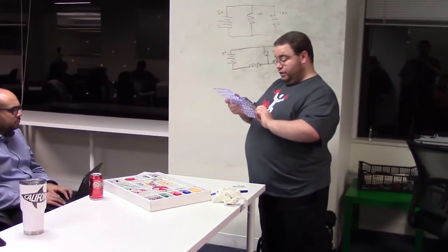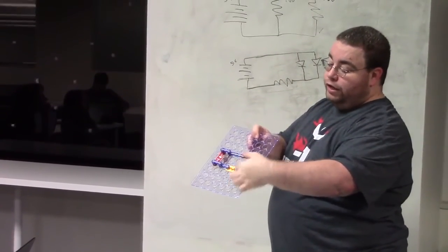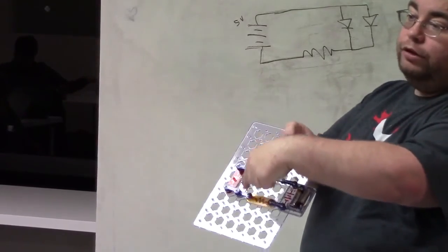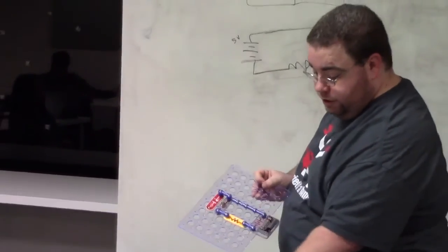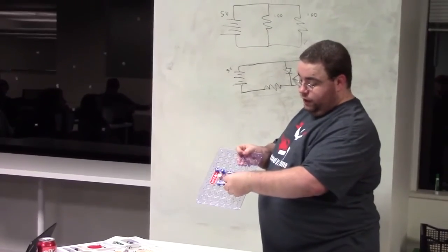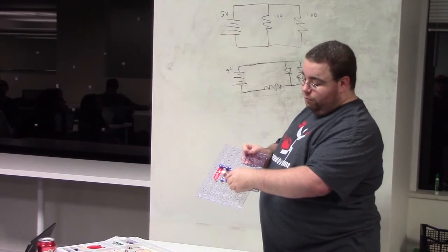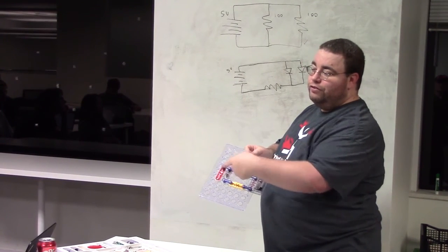So here, I have actually built that. What's happening is because the resistor is in here, it's keeping there from being enough current flowing through here to light the light bulb. If you replace the resistor with just a wire, then it'll light the light bulb. See, it has bypassed the resistor. The problem is if we do that, that's going to be too much current for the LED, and so it'll explode.